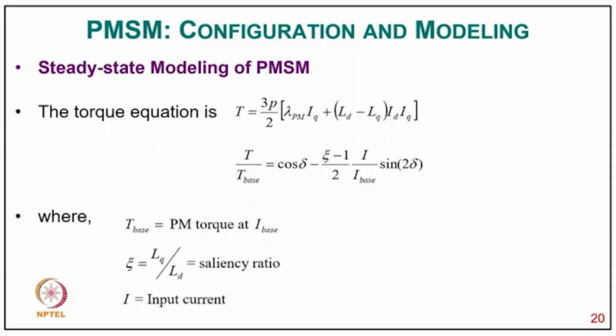So that's very useful for electric vehicles with a high starting torque, and then to get a constant power characteristic over a wide range for very high speed. Since magnets are put into the flux barriers, the machine has a very robust construction to achieve high speed.